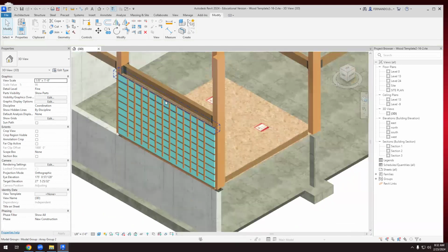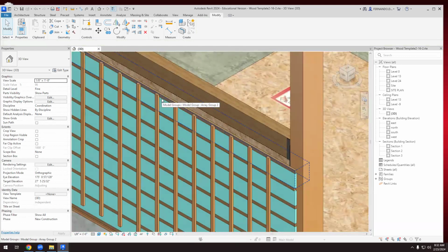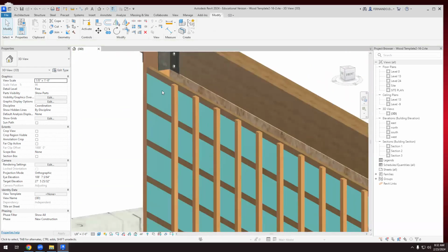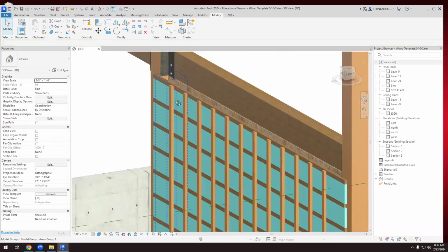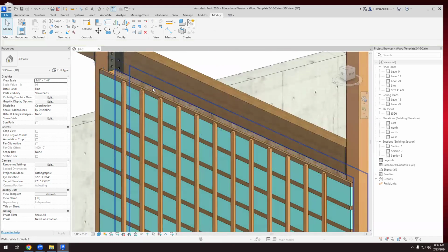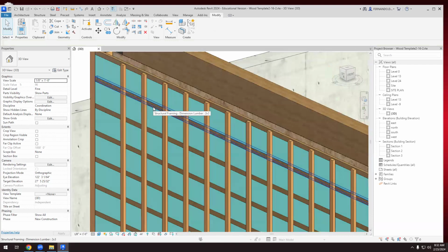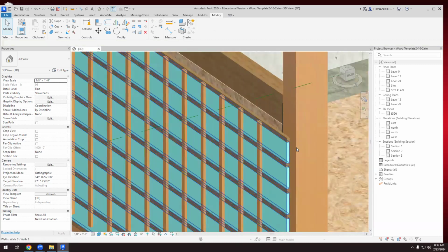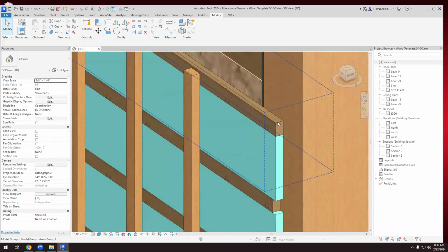So now I can fill this cavity with thermal insulation. In this case, there will be vertical panels, but if we have a vented facade, I think it will work well because if some water gets there, you dry out by having a ventilated cavity there. So I'm not going to fill the thermal insulation. Oh, and look at what I did here. I didn't do that detail that I drew.